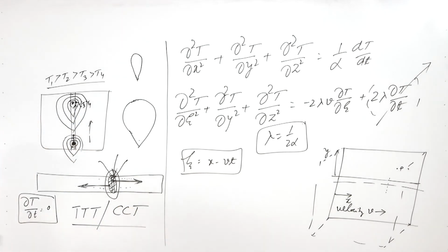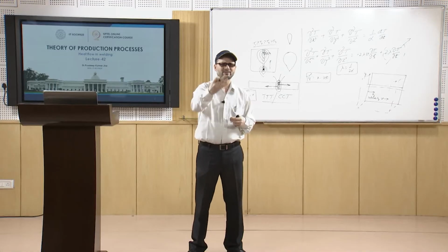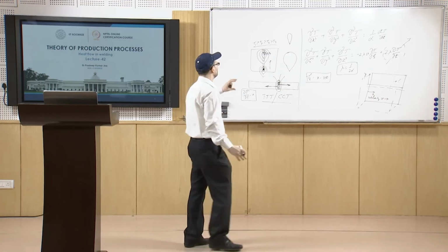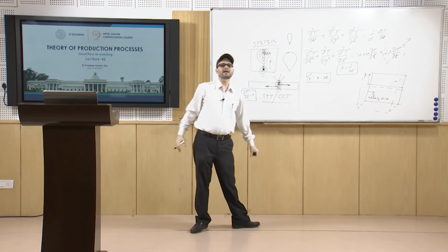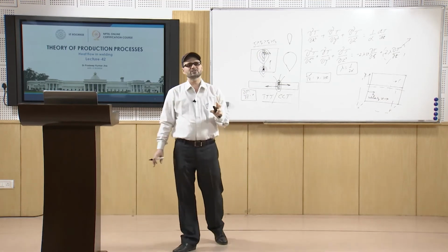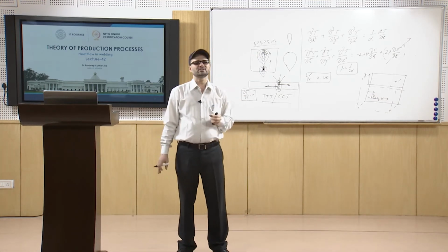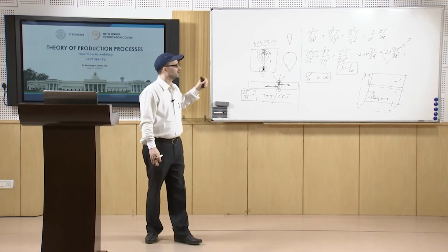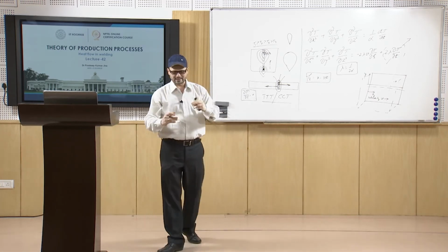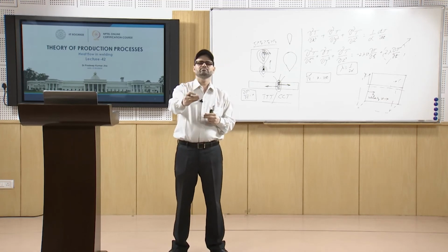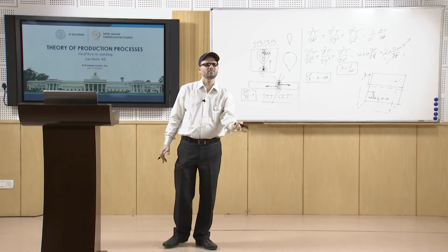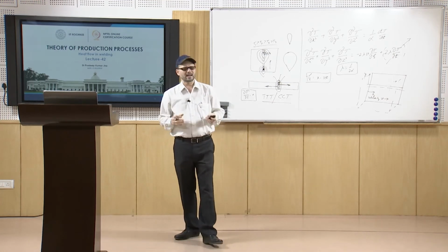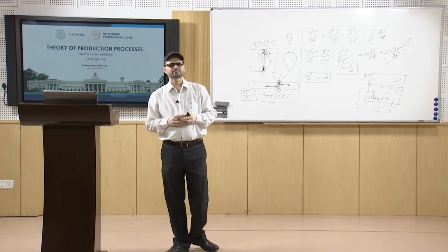So, how do you see the isotherms, and depending on the spacing at different points, you can predict the microstructure and the mechanical properties in such cases. So, this way you can say that here the phases will be like coarse pearlite or fine pearlite or bainite or martensite or so. So, depending upon that you can predict that.